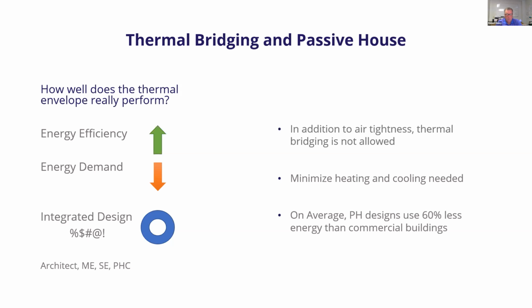With Passivhaus, this involves a very, I wouldn't say rigid, but all parties need to work together on the design of the building, meaning the architect, the structural, the mechanical, all need to be on board on day one talking about these details, simply because, look, if you're the mechanical engineer, you need an accurate balance point temperature in order to design the plant for the building, to size it properly, to reduce cost, etc. And so everybody needs to play together and figure out, how are we going to obtain this goal of low thermal conductivity at our interface details, which isn't always the case out there in the real world. So collaborative effort is important.